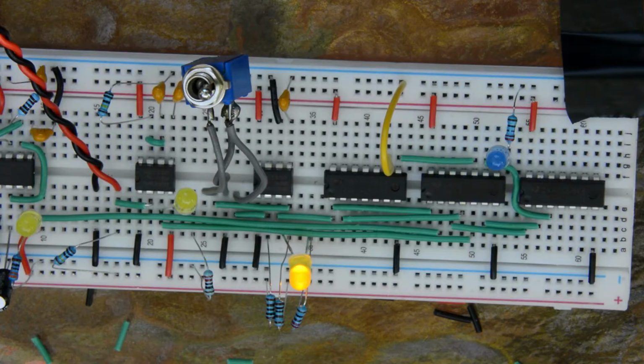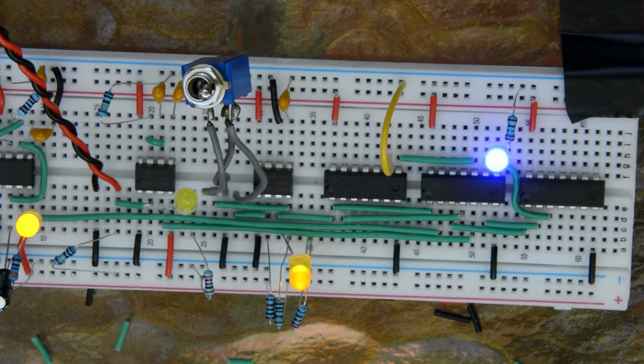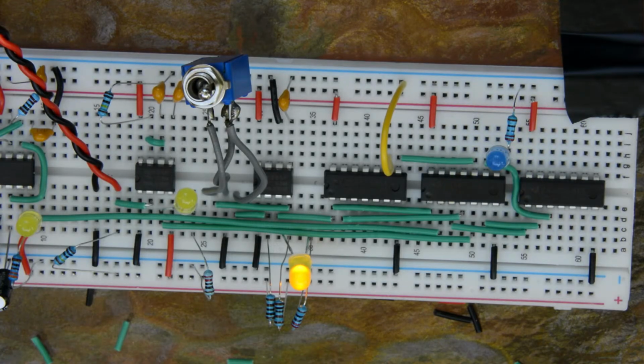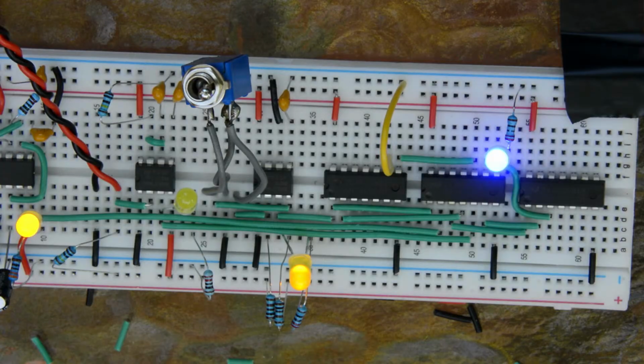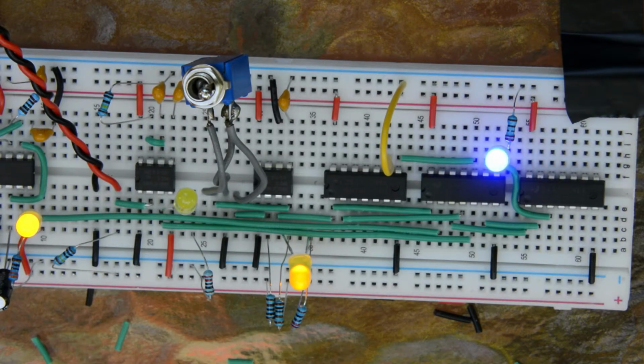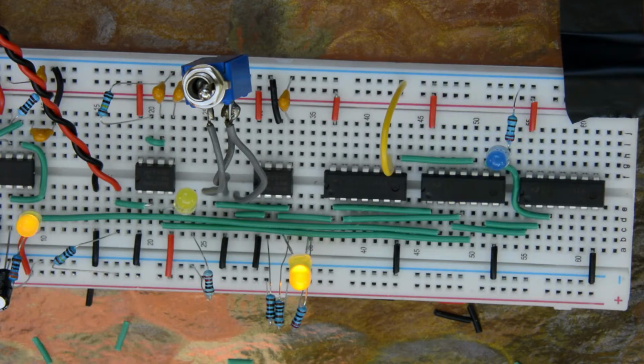This is Ben Eater's clock module, and it uses 3 555 timers in different ways, and then a couple of logic gates to combine the outputs here so that you can control your computer with a clock in 2 different modes. The 2 different modes are selected by this switch, so now the output of the clock is off, but there's a button here that lets me step the clock so that I could manually step my computer forward.